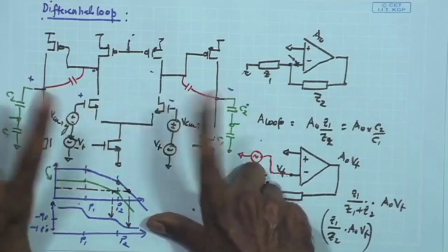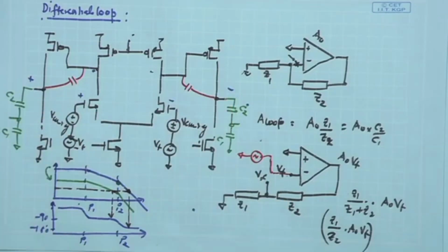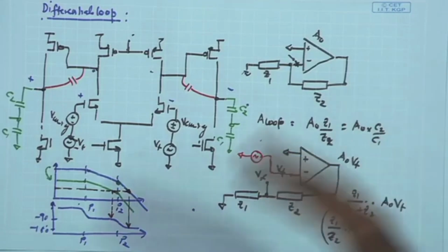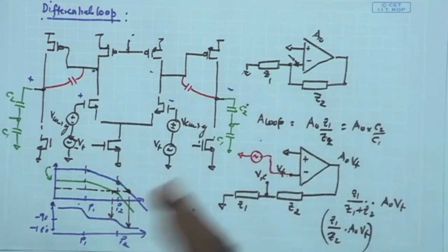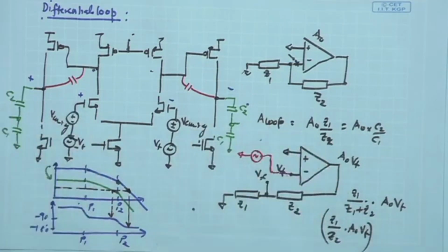Effectively it is not contributing much to the overall frequency response, apart from, of course, the high frequency behavior that comes into picture when you look at the closed loop response, and you have that high pass filtering mechanism provided by this RF. But for stability analysis, it will not play a very significant role.